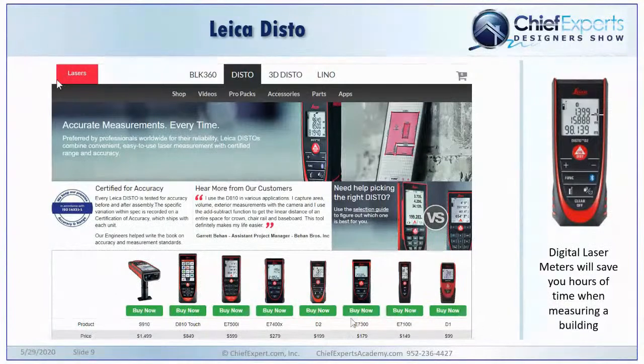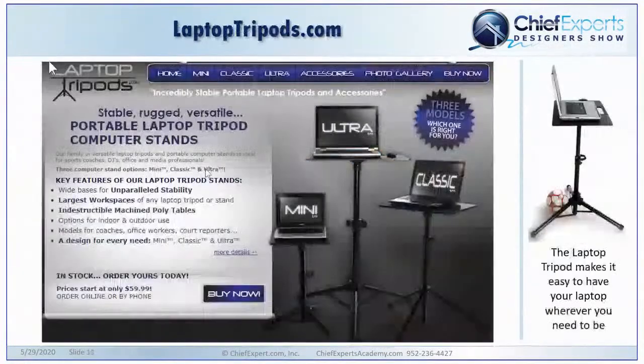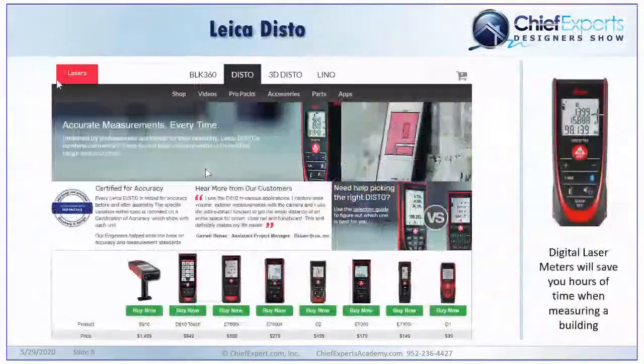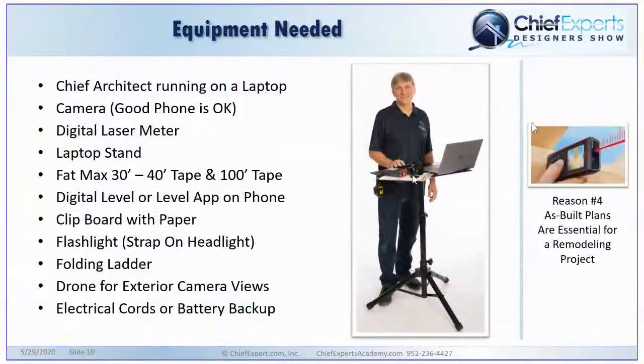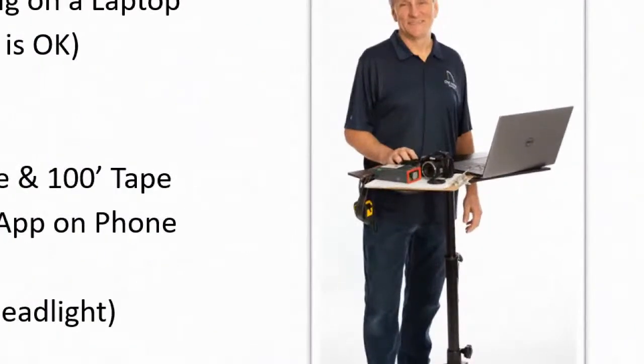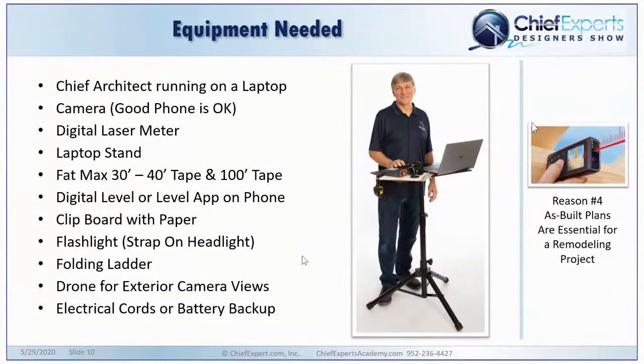Yeah. So again, depending on what you know, even if you just have a basic one, whatever you do, if you're going to go measure a building, you have to use some form of a laser meter. It will save you a ton of time. I mean, basically, you're going to have all the equipment that you need anyway. So with me, it was always my laser meter, my tape, my camera, which I take a lot of pictures. I'd have a 100-foot tape that I'd use if I needed some really long ones, and I couldn't get my laser meter to work.